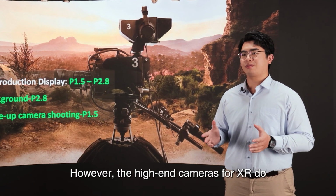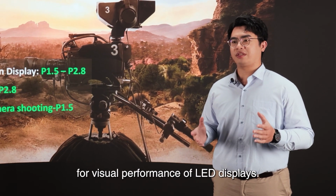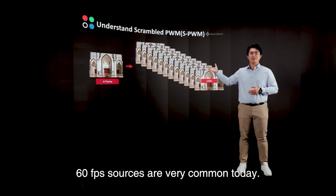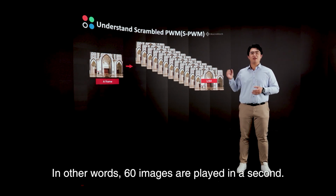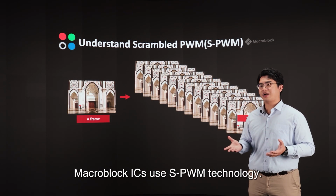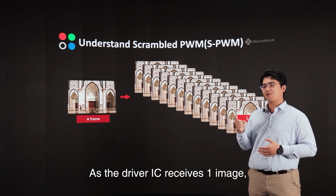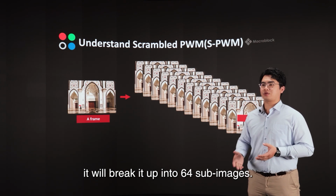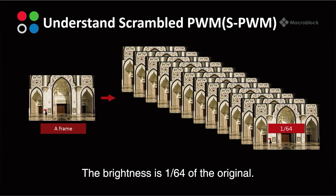However, the high-end cameras for XR present some technical challenges for the visual performance of LED displays. 60 FPS sources are very common today. In other words, 60 images are played in a second. For smoother video playback, Macroblock IC uses PWM technology. As the driver IC receives one image, it will break it up into 64 sub-images. The brightness is one of 64 of the original. We call this technology Scramble.